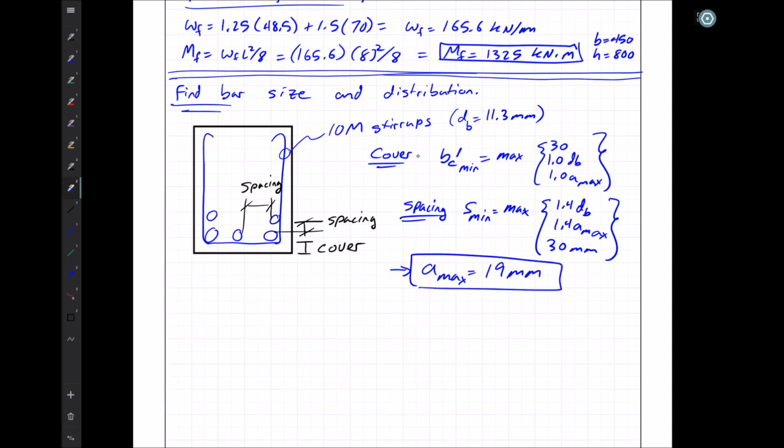And this is a somewhat default value as well. There are a bunch of reasons why we would use bigger or smaller maximum aggregates in the concrete, but that's not for this particular topic here. But they can have to do with the size of the forms that we're working with, or the size of the cross sections, what we need to flow into what materials, or into what zones. And as we get higher strength concrete, the aggregates start to become the weak part of our concrete mix.